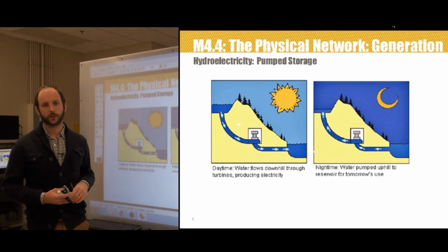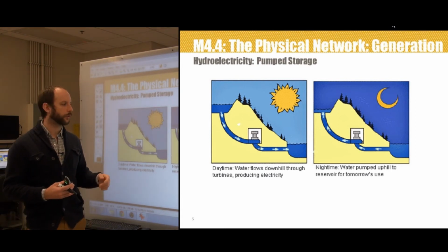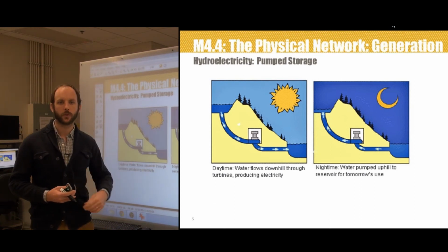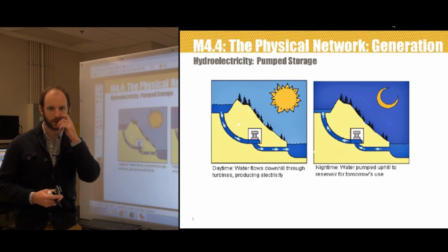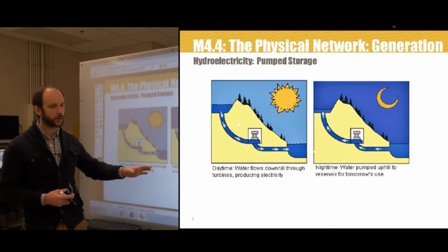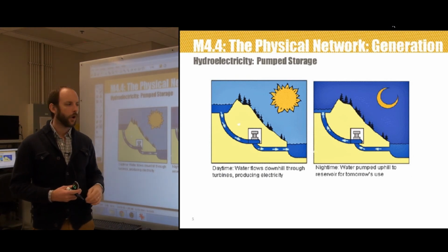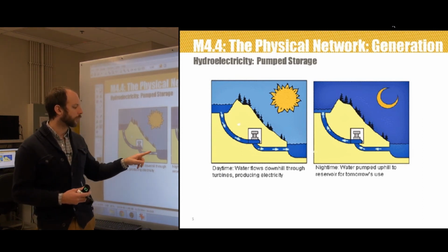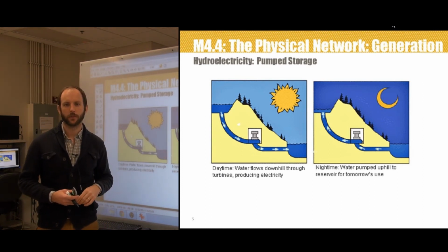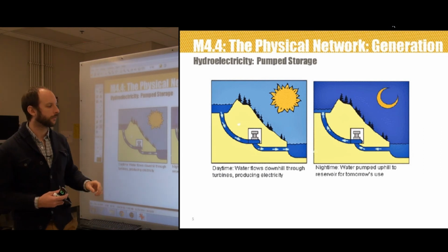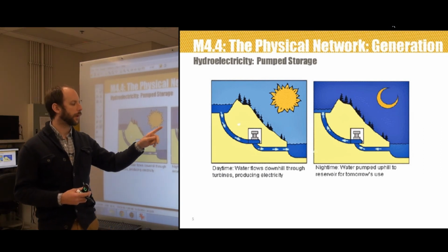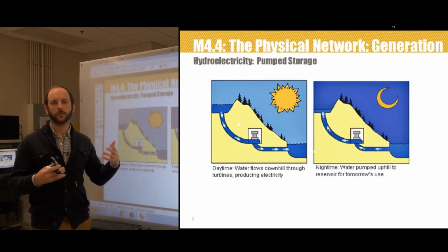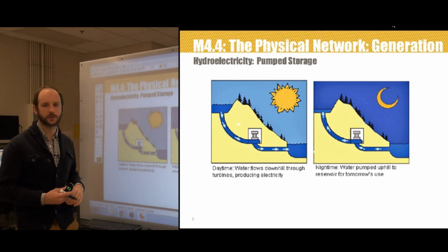Pump storage facilities produce electric energy from generation, but also clearly they consume energy when the water is pumped uphill. That takes electricity. So if we consider the total energy balance of such a system, only about 2/3 of the energy that we pump up is reclaimed. So we lose about 33% of the electricity in doing this.